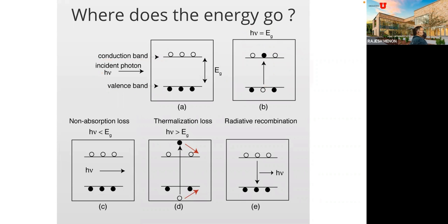Now, of course, many other things can happen. This is not the only thing. If the energy of the photon is less than the bandgap, the photon does not have enough energy to kick the electron out of the valence band. It won't be absorbed. It will pass straight through, as shown here. And this is what happens in the case of glass, right? Glass is transparent to visible light because nothing is absorbed, it just passes through. The energy is not enough for the bandgap of glass; silicon dioxide's is too high. Silicon dioxide, by the way, is amorphous, so it's not an exact analogy, but imagine that.